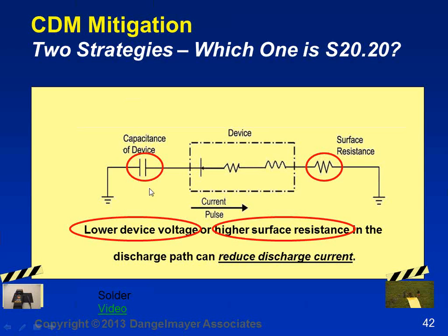How do you keep voltages down on the product? Well, you have ESD mats, wrist straps, and ionizers. Valuable tools. However, they're prone to human error. They're often facing the wrong way, turned off, dirty, not calibrated, etc. Whereas if you take a material with the right properties and put it in just the right location, you can prevent damage, and it will need minimal maintenance.